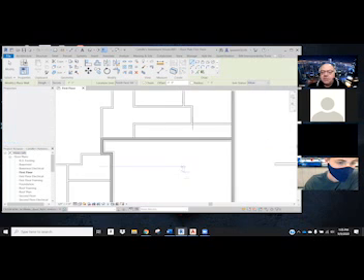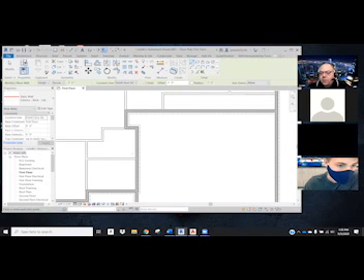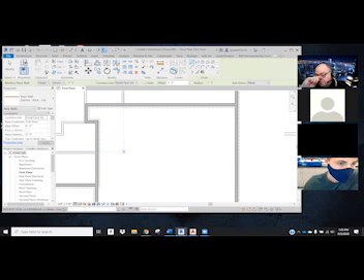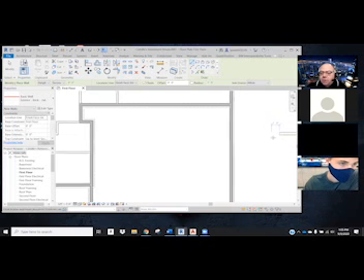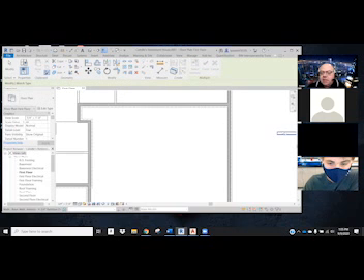Okay, so that finishes my perimeter. But if you notice, my inside walls have brick. And that's a bad thing. I don't want brick inside. That's really expensive, first of all. I'm a fan of putting drywall and finishing the garage so it's a finished space and not raw wood, if you can afford to do that. But now I've got this little piece of a wall over here on the side. I'm going to go into Modify tab, use the Match Properties, select that little wall piece, and change your interior walls to the correct wall type.